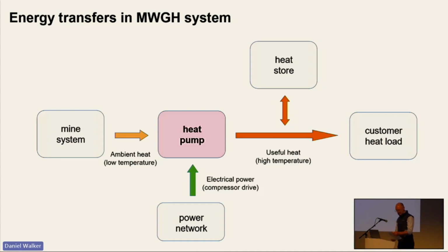Anyway, after that slight digression, we'll come back to the question that I posed a couple of slides back. How can a standard design solution work for different mine water projects given the variability of parameters such as the mine water abstraction temperature? And to answer this, we're going to dive into the world of heat pump design for a minute or two. Now, we all know that heat pumps play a vital role in mine water geothermal systems. What I'm going to show you is that they're also quite flexible devices that can operate reasonably well across a range of conditions.